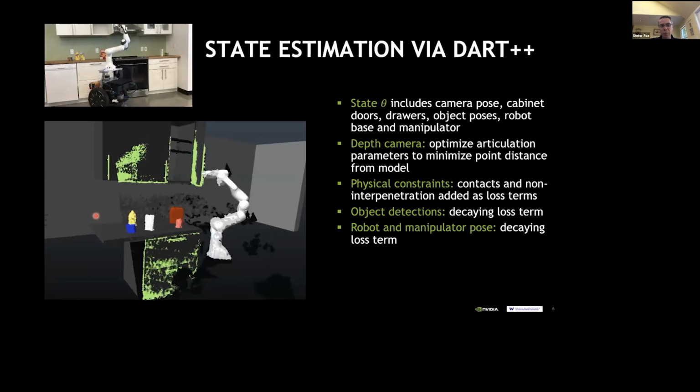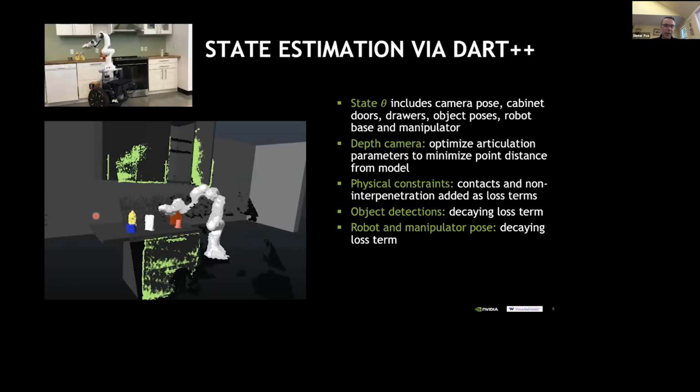So you can see this is the robot, where it used the model for planning, and then it can also execute it by keeping track of the objects and then using that explicit pose estimation in order to execute the actions. Now, I'll anticipate this, but one of the main limitations is really the reliance on the 6D pose estimation, because as soon as that estimation is not very accurate because of occlusions or things like that, the grasping itself might break down. But otherwise, it works pretty well, as you can see here.